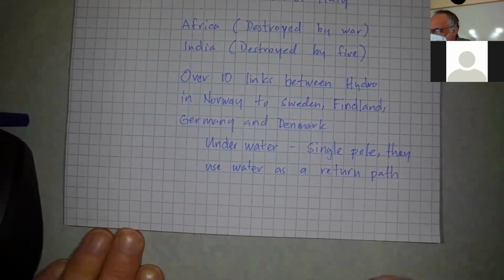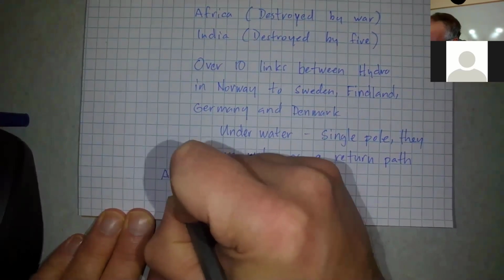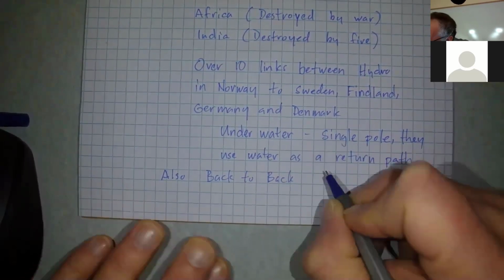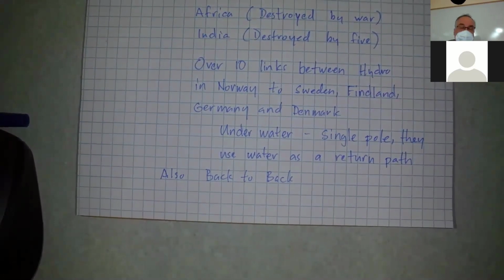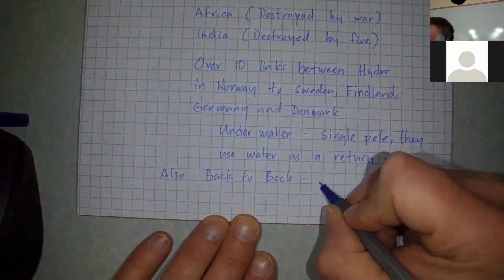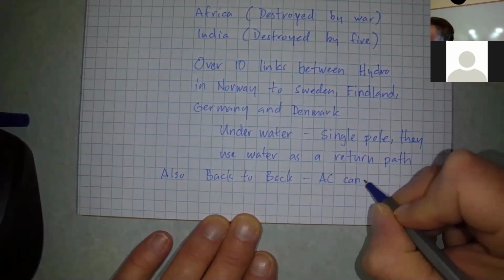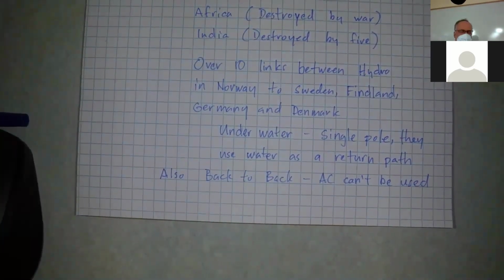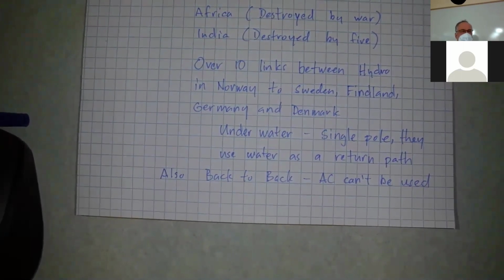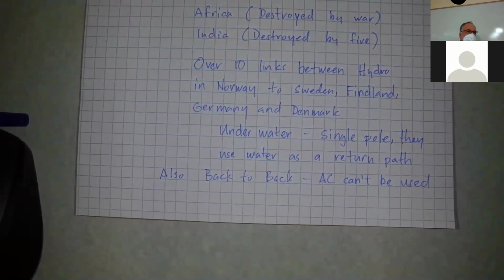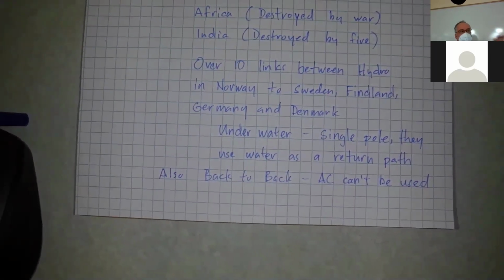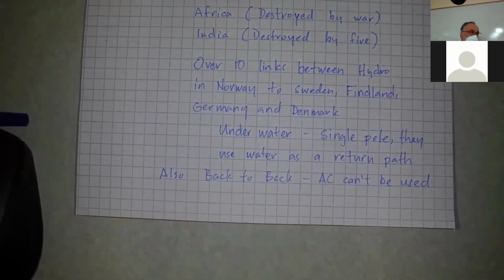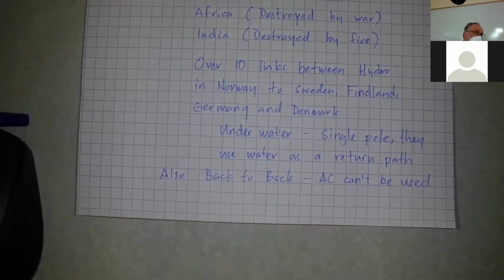Okay. In the little bit of time that's left, now, back to back, it's not for great distances, but if you look at the Lower Peninsula and the Upper Peninsula, the Upper Peninsula is closely tied to Wisconsin, right? And so the phase angle on the power grid is similar to that of Wisconsin. Lower Peninsula is at a different angle. So if we want to ship power back and forth, we have to use a high voltage DC link.